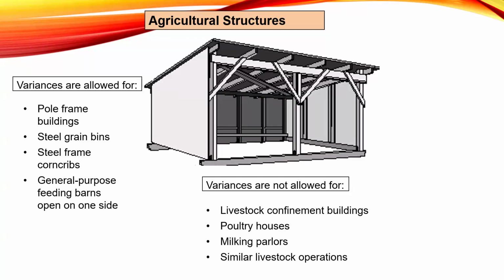So the same thing for garages and accessory structures, we can't count a door as a flood opening. It has to be permanently open or able to be opened by the floodwater. So we can't count a door. You can put an opening in a door, like a garage door.